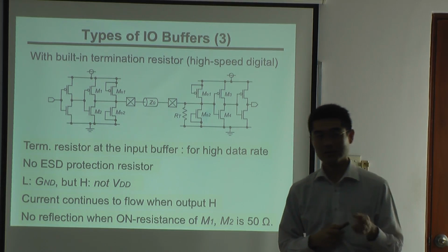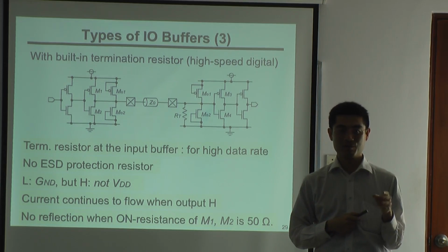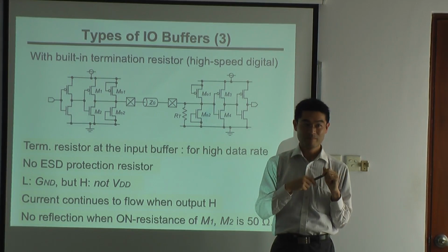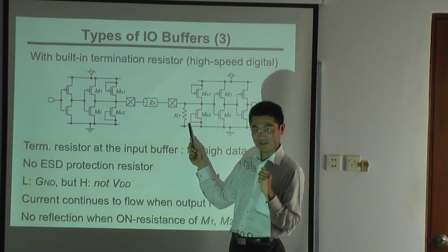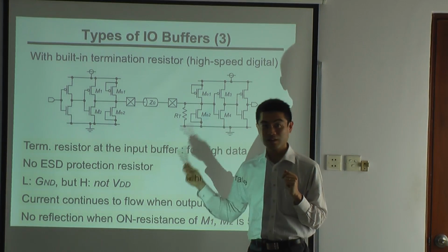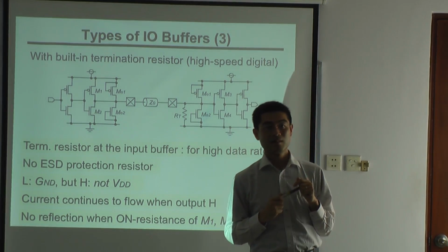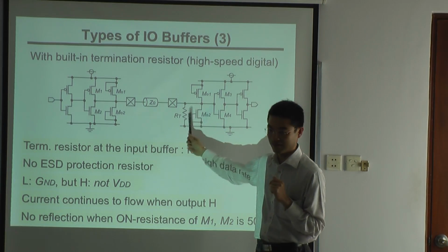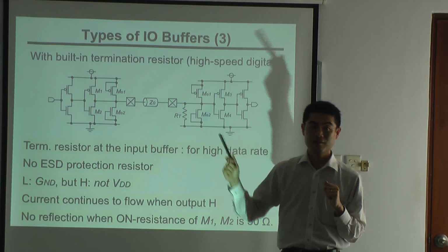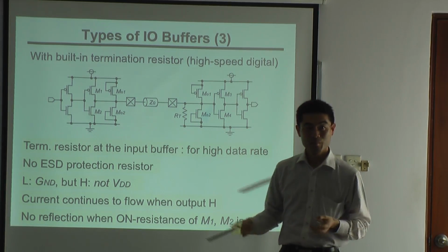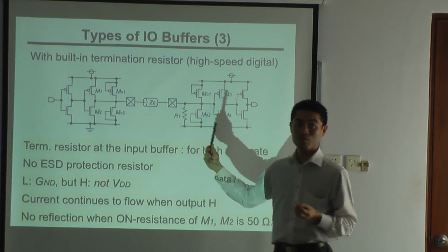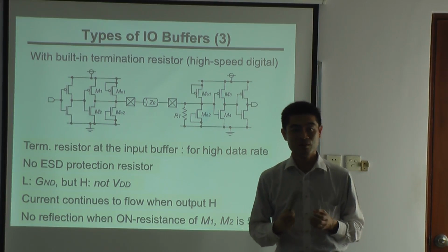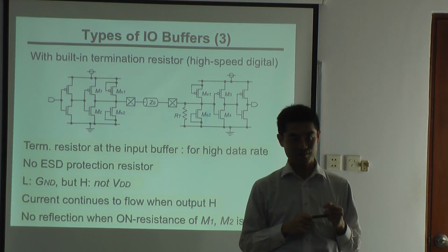Yes, that's the same question. Receivers usually have termination resistance. So in this case, it has high immunity against ESD. So it often happens that it will pass the ESD test even though it does not have an ESD protection circuit, because this termination resistor works as an ESD protection circuit. And if it fails, you will negotiate with customers and quality assurance.